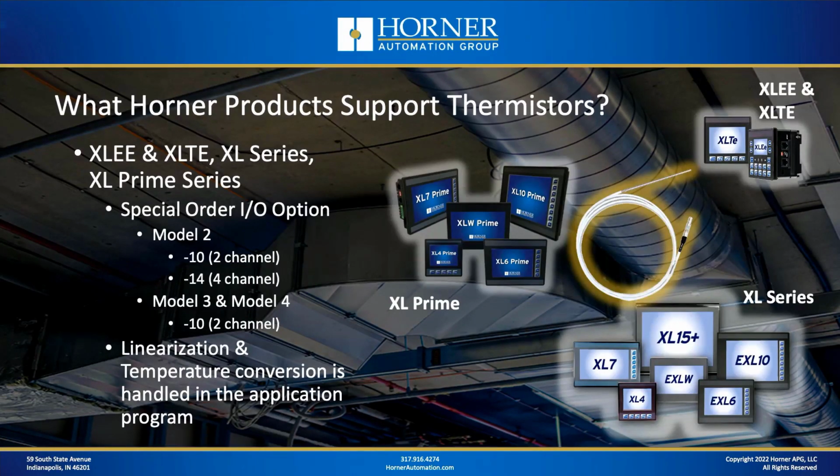Now, you can also find thermistor support as a special order I/O option in the XLE and XLT, the XL series, and the XL Prime series. So the Model 2 I/O option is available with either a 2-channel or 4-channel special order option. The Model 3 and Model 4, which have solid-state outputs and slightly different mixes in general, have a 2-channel option for thermistor. Now, because this was added after the fact as a special order, the linearization and the temperature conversion is handled in the application program. So that's not something that the firmware of the OCS handles automatically. That needs to be handled in your program.